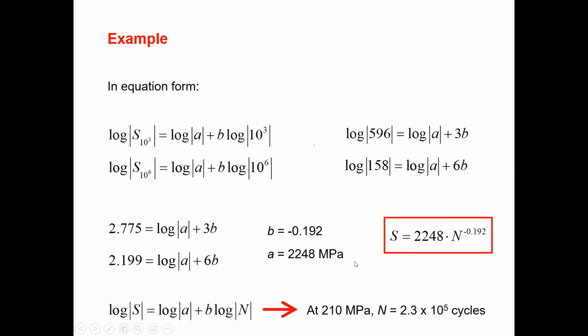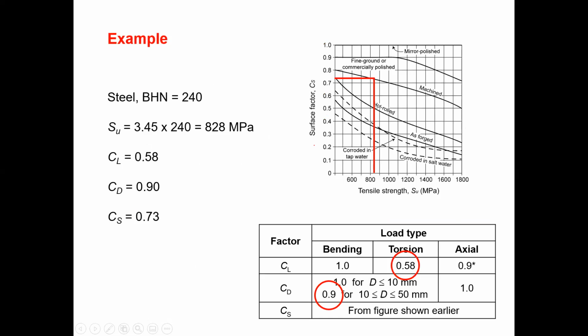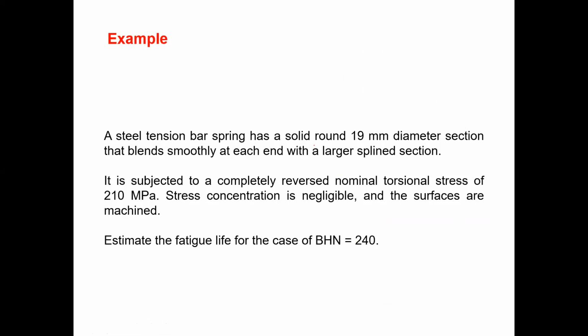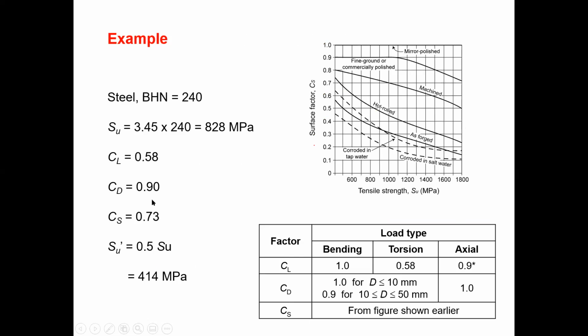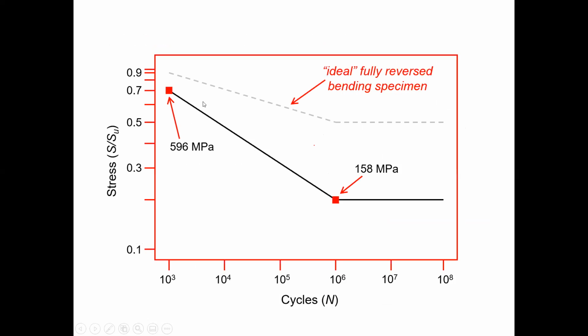So what you can do now, if you know the stress. In the question, I will go to the question again. In the question here, the stress is 210 megapascal. So if you know the equation of this curve, and you know the stress value, you can find out the fatigue life. So you are going to find out these 2 points to derive that equation. Derive means you are going to define that equation. So after defining that equation, you can substitute the x coordinate or y coordinate and find out the other coordinate.